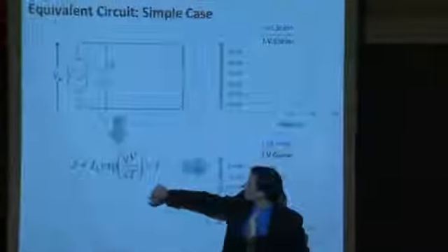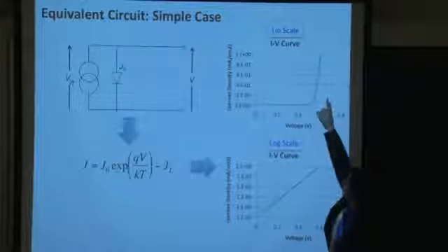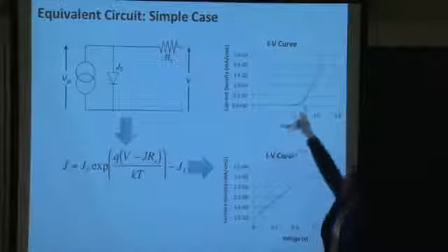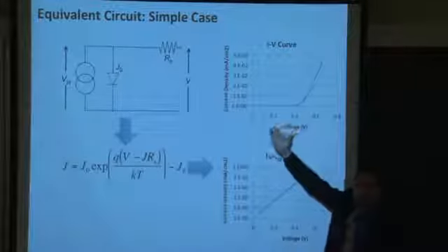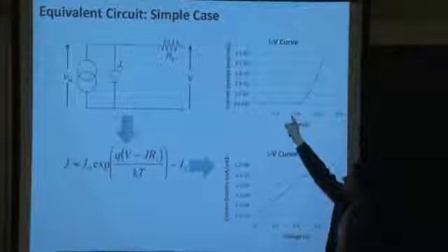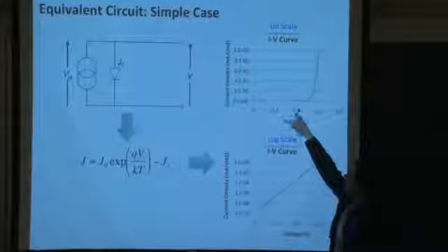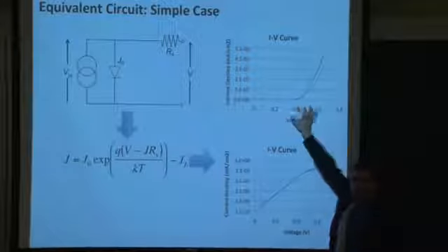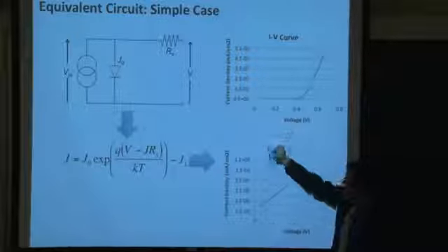Well, we'll go back once again to our ideal diode equation right here. We have a very sharp, box-like IV curve under the ideal conditions. Now when we introduce the series resistance component, we begin smoothing out that IV curve. The fill factor has dropped. Take a look. Ideal conditions: sharp, very large fill factor. Now we've added the series resistance component. The fill factor has begun dropping.